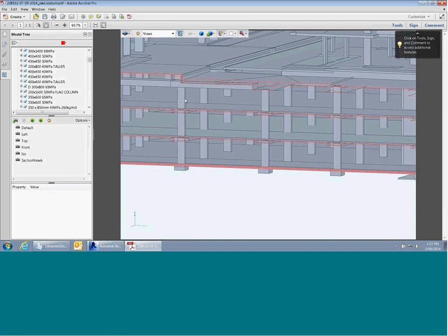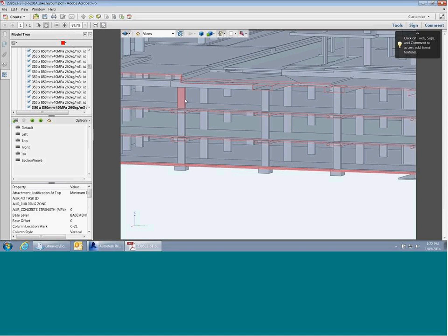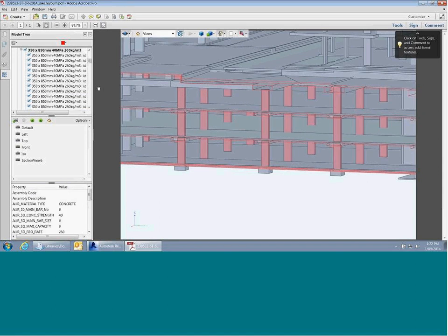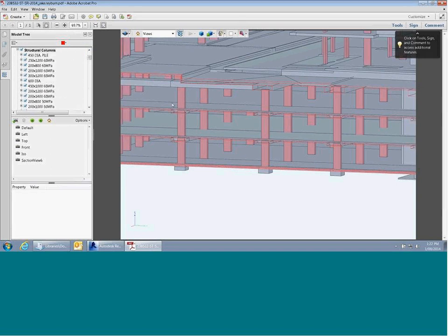It's actually in the name. That's the type name, isn't it? Yeah. So the first time you select it, it'll go right to what it is, and it will have its individual ID number. If you click on that again, it will search all the instances in the model. If you click it again, it just selects all structural columns.